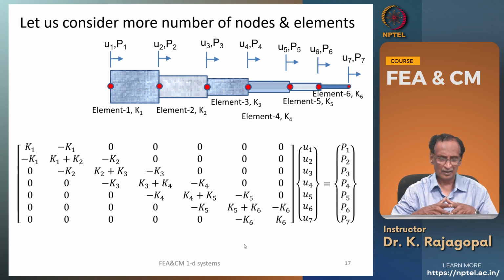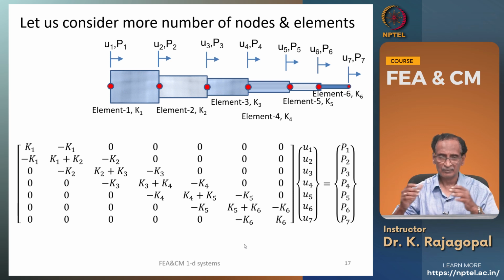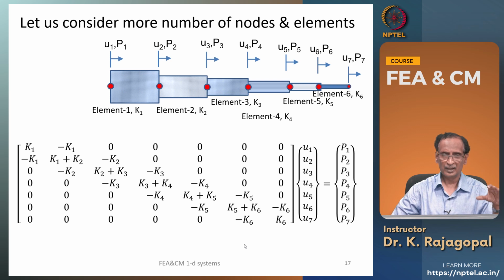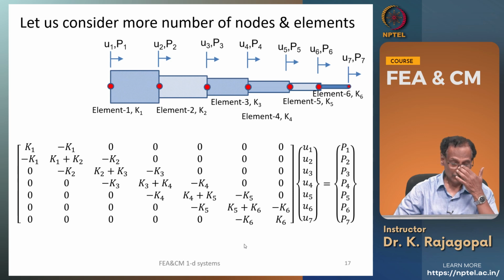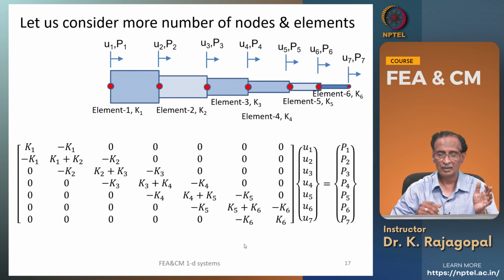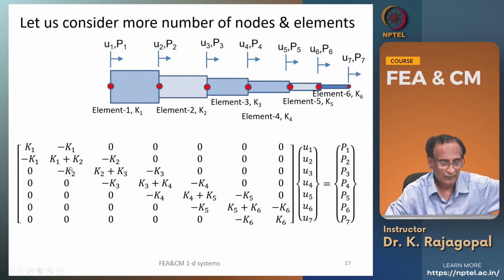And the determinant of this bigger matrix is also 0. That we do not need to doubt, because at one element level we have seen, then we can extrapolate the same thing, and even for the 2 element case where we have a 3 by 3 matrix, we can theoretically calculate and see that the determinant is 0. And if you take a lot of effort and find the determinant of this entire matrix, you will see that it is 0. We do not need to actually calculate.